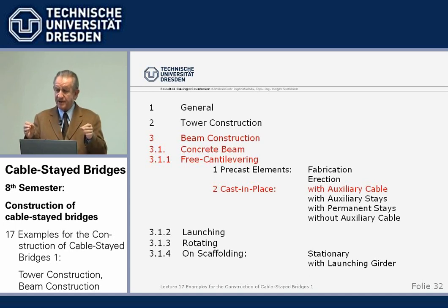And they have, say, 1 year or so of age when they are installed, so their shrinkage and creep capacity is greatly reduced against cast in place fresh concrete. Disadvantage is heavy weight, 300 tons for transportation and lifting. And how do you do the joints? Either match cast glued or cast in place joints.